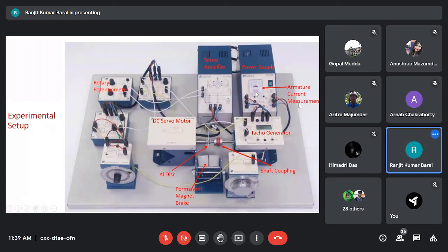Okay. Servo amplifiers are linear amplifiers. Their characteristics are similar to audio amplifiers. Okay, they are very costly. Their bandwidth is very wide, and their characteristics should be perfectly linear, so that the control signal that we are feeding to it should not get distorted. It should just amplify. It will amplify the voltage waveform. It will amplify the current waveform. So it will give power gain.